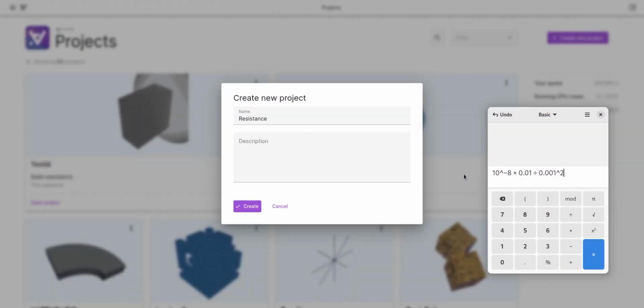In this video, we will show how to compute the DC electric resistance of a wire of square cross-section. Now, this procedure applies to any geometry, but in order to compare it to an analytic value, we will use a constant conductivity of 10 to the power 8, a length of the wire of 1 centimeter, and a square cross-section of 1 millimeter side. And using Pouillet's law, we should get exactly 100 micro ohm resistance.